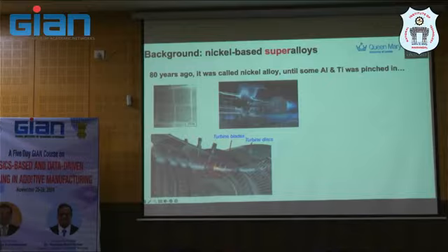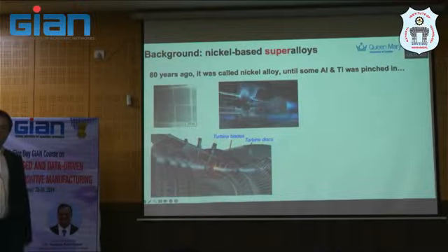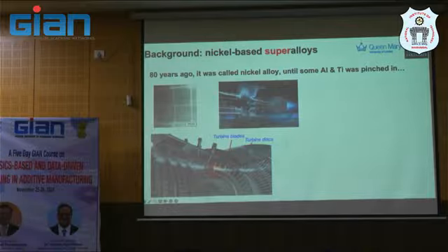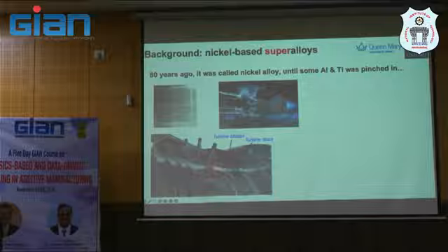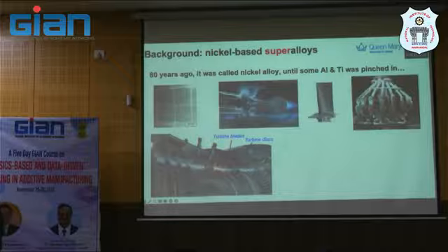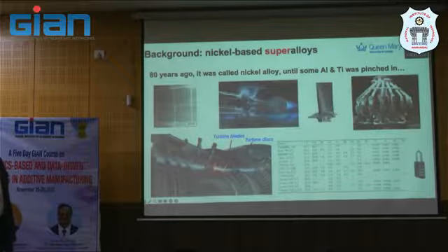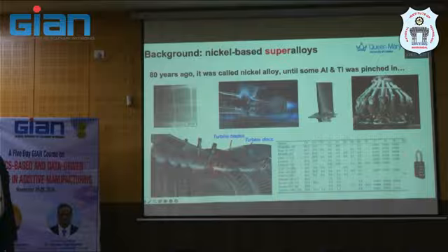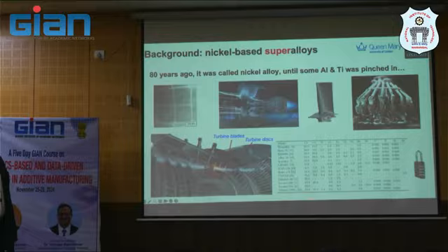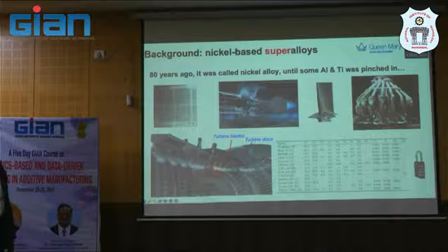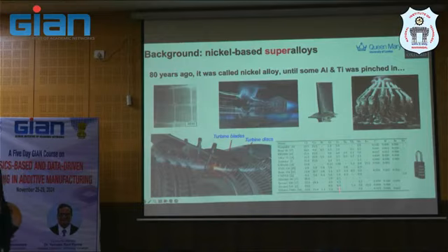When I say high temperature, it's performance at least above 850 degrees centigrade or above 1000 degrees centigrade. And then we're focusing on the critical parts like disc or blade material. If not a single crystal blade, it will be some other blade made from Inconel 718. And traditionally, we use casting, and this is a kind of composition available, also based on the benchmark of the nickel-based superalloy we are considering. So you will see it's about 13, 14 elements that form one alloy system.